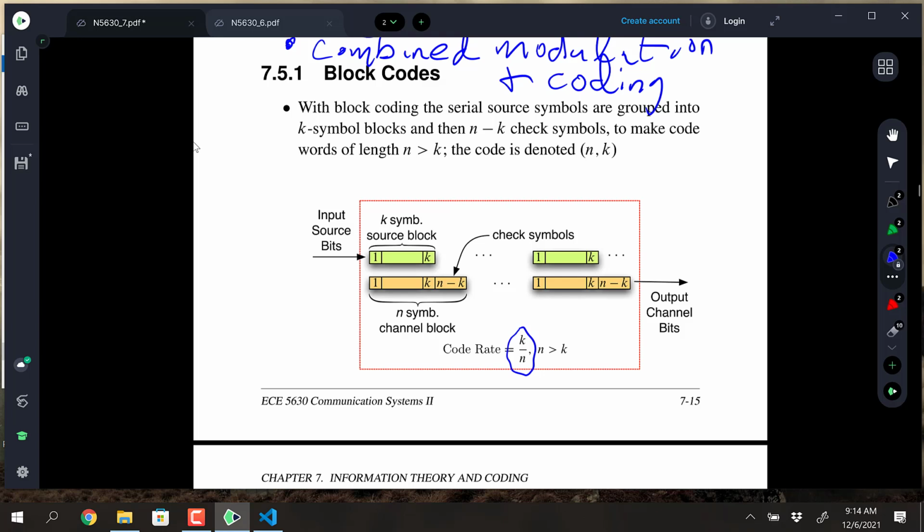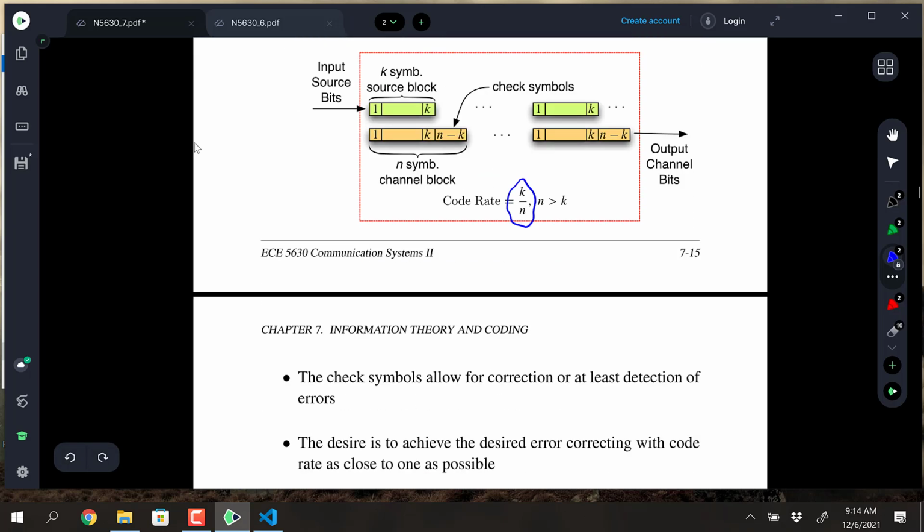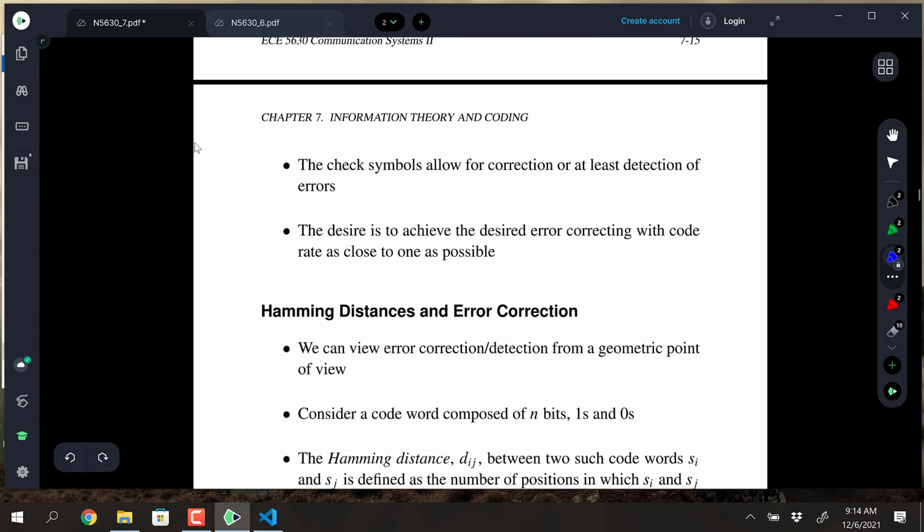In hardware we have things called gearboxes, which handle the rate mismatch between input and output, and it's a bit involved in your ASIC or whatever, because you need to handle the unequal rates on either side. It's kind of like DSP, where you have rate changing going on. Yeah, exactly.